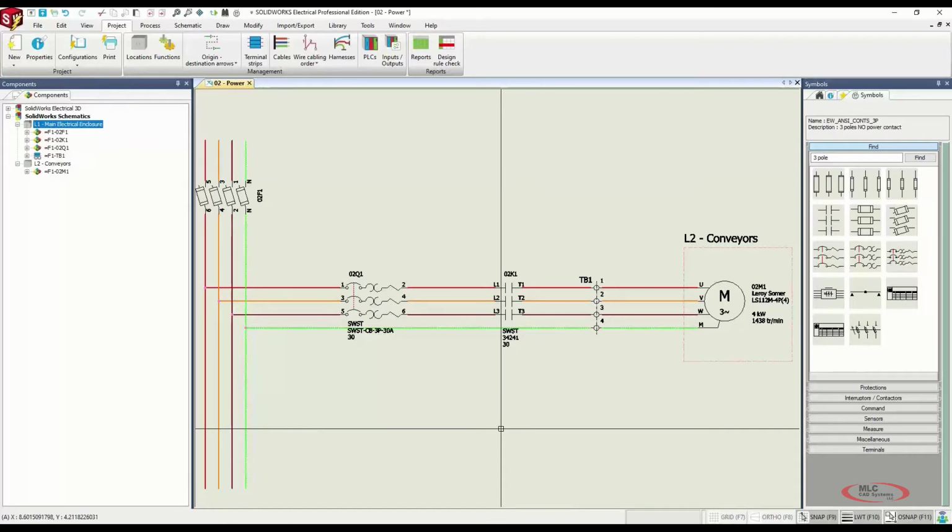Now, those wire styles come into play because the wire styles carry formulas to name themselves. So if you wanted a wire style to carry its color, its gauge, and its from to component, you could create a formula that would name the wire exactly the way you wanted. So that kind of leads back into that setup. The setup for SOLIDWORKS Electrical is pretty critical. It's one of those things where if it's set up properly, you never have to think about it again. If it's not, then you might be battling it for a while. So make sure that you set everything up correctly in the beginning, and all the formulas then just work magically down the line. We call that the auto-magic way. At least I do. I mean, I'm a super nerd, right?